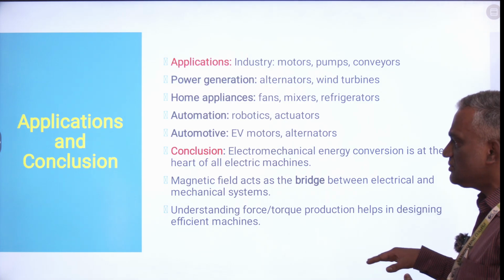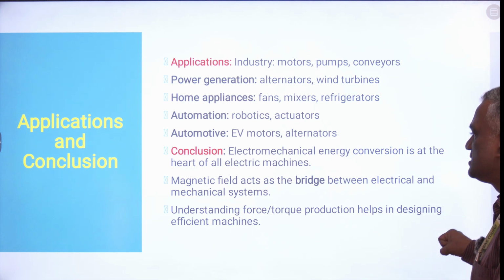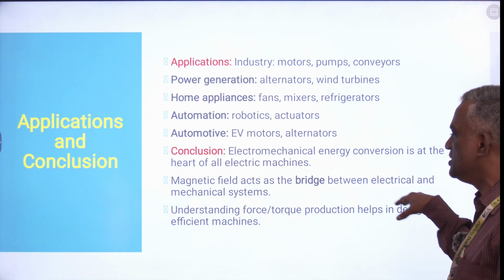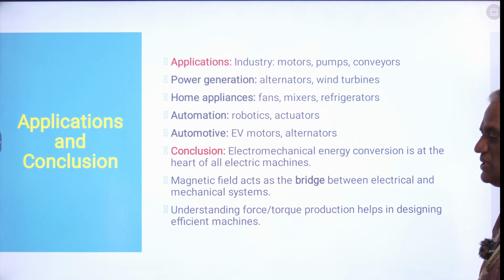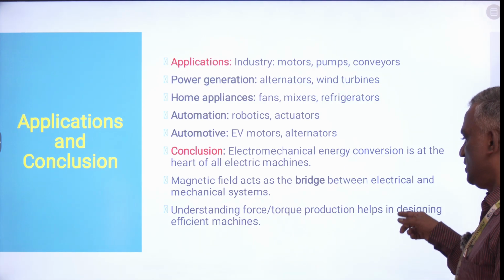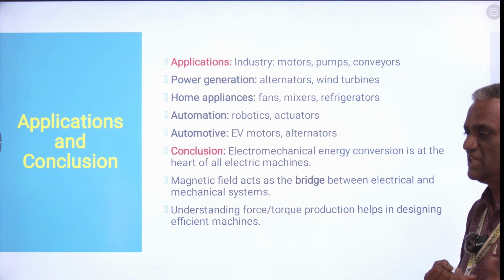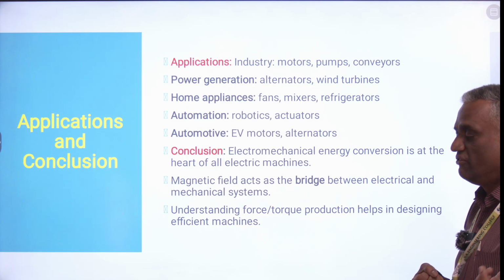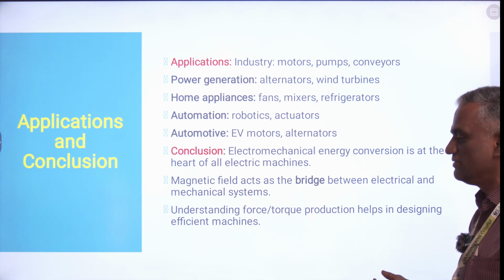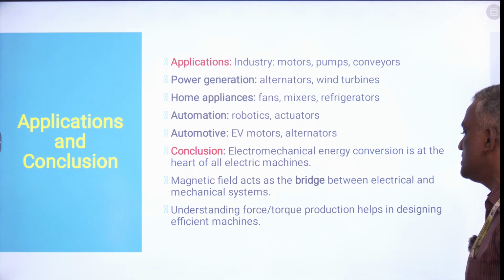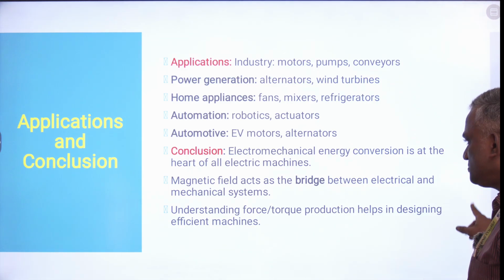Fine. So to put it in a very simple sentence, we have taken the energy conversion, electrical to mechanical or mechanical to electrical. The bridge between these two is the field. That field is actually called a magnetic field. We have also taken another important topic, how to calculate the force as well as torque. The force and torque are calculated with the help of the energy stored in the field, that is nothing but field energy. Along with that, you have the co-energy also. That co-energy has been taken, and then we derived the force equation as well as the torque equation. So this is very important.